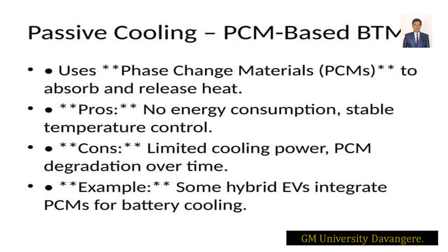All right. When you talk about heat capacities, the PCM is limited to 150 to 250 kilojoules per kg. That is a limitation for the heat capacity by mass. Temperature control: it can hold up to a melt temperature of around 35 degrees centigrade. And the response time, the PCM is not faster. Sorry, it takes a minute to melt. It will take a very slow time to melt. It takes more time to melt.